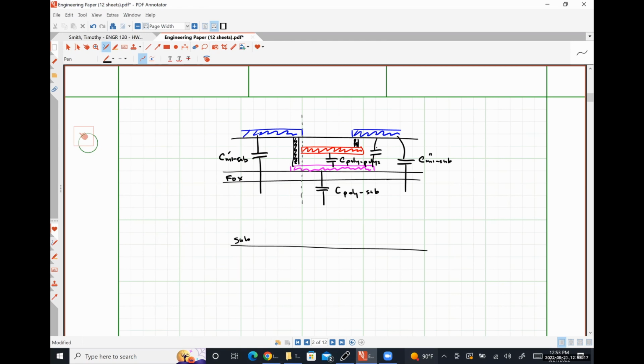Yes, but that part's going to be pretty small, assuming that you are designing your capacitors such that your poly 1 plate is as small as it can possibly be to accommodate your poly 2 plate, which is generally going to be the case because the larger you make your poly 1 plate, the larger your bottom plate parasitic capacitance is. So there will be some small contribution there.